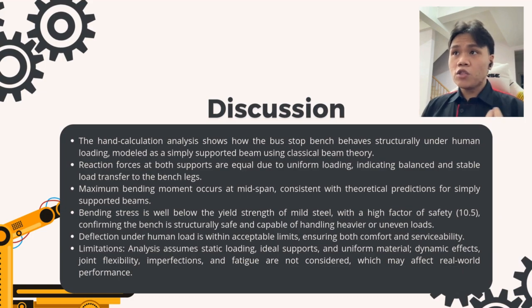Bending stress is well below the yield strength of mild steel, with a high factor of safety of 10.5, confirming the bench is structurally safe and capable of handling heavier or uneven loads. Deflection under human load is within acceptable limits, ensuring both comfort and serviceability.